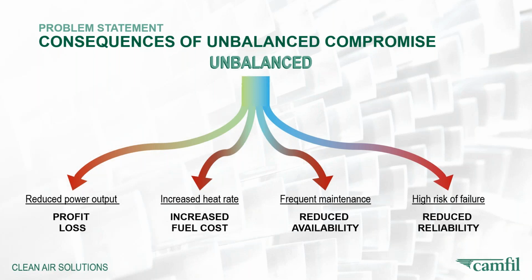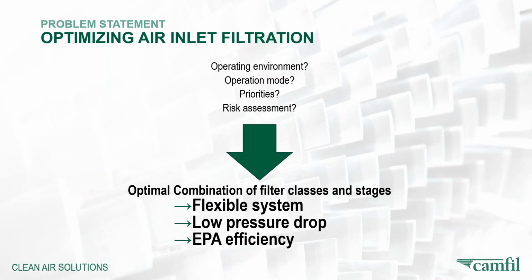And even more, if you have really inadequate filtration solutions defined based on environmental conditions, you may end up having very frequent stops on your gas turbine, needing to do frequent filter changes, needing to do offline washing. And eventually, if you really have a bad filtration solution, the risk of hot corrosion issues, creating havoc on your turbine section, could actually lead to failures.